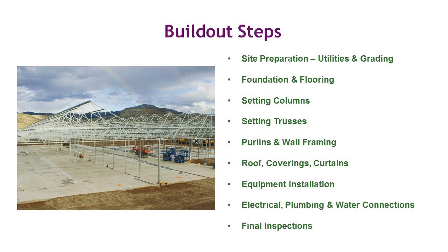Ultimately, labor costs. So once you've got your purlins and your wall framing up, then you can start putting your coverings up. Depending on the time of year, you might put your roof up first if it's wintertime, or if it's spring and you're getting rained on, or you might put up your wall coverings and the curtains first if it's the summertime and you want to be out of the heat. By not putting the roof on, you'll be able to work inside a little bit longer until you bring power to all the equipment.